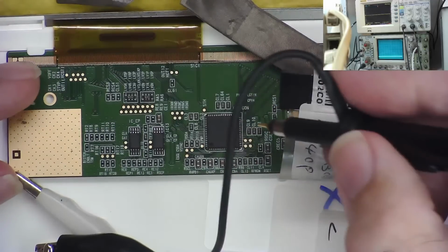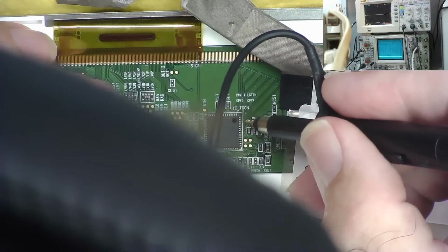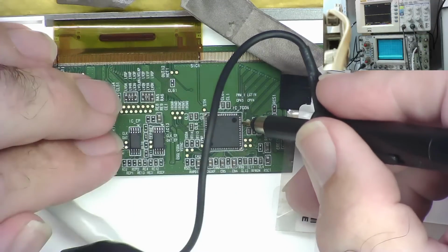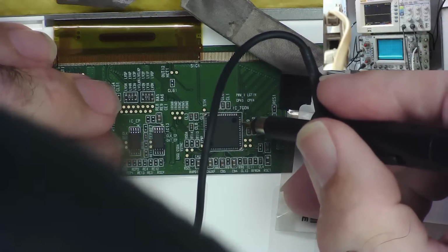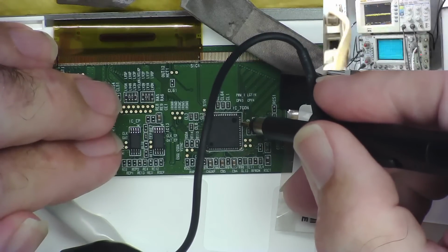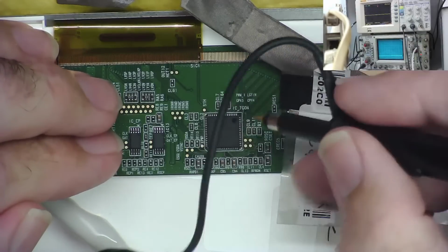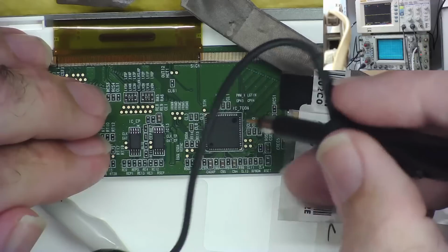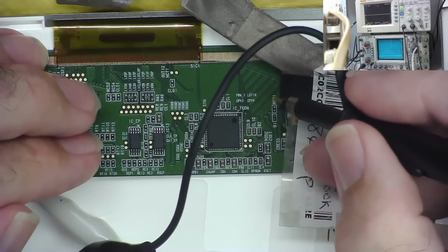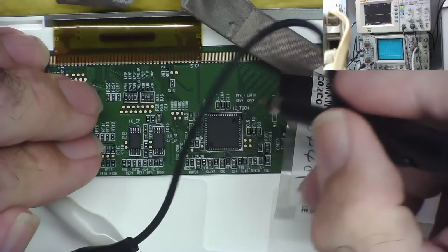But let's go on the output of this chip. This should be able to tell us. We should be able to at least see it driving some data up towards the screen. Let's just go onto one of these pins without the magnifier. Yeah, that's one of the output pins, and you can see there's data on it. So the chip is definitely driving data up towards the screen. I don't want to probe around too much. I've got no magnifier, and I might just end up shorting something using effectively the naked eye. Can't get a connection onto them now.